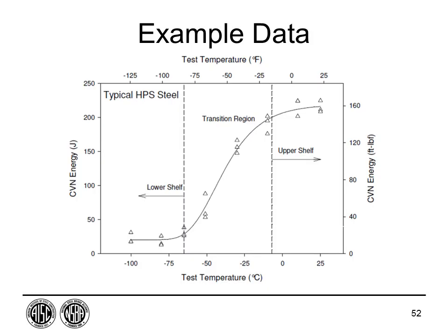What happens when we do those kinds of tests is we measure the energy, whether we're in joules and Celsius, or if we're using foot-pounds and Fahrenheit. But we see some interesting things here. At lower temperatures, I have less energy absorption. As I begin to warm the specimen, I begin to be able to absorb more energy. In other words, the material is getting tougher. And this same type of curve actually matches what we would see for a true toughness curve.